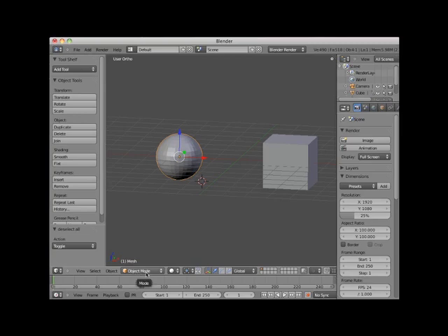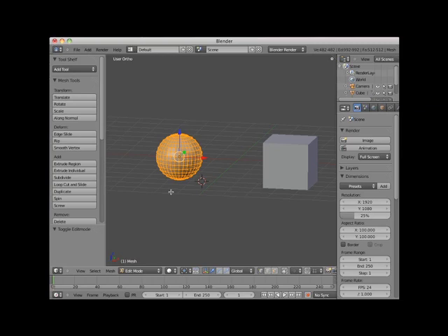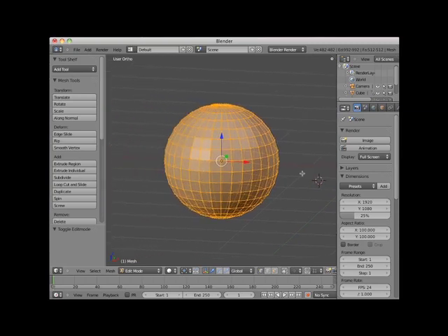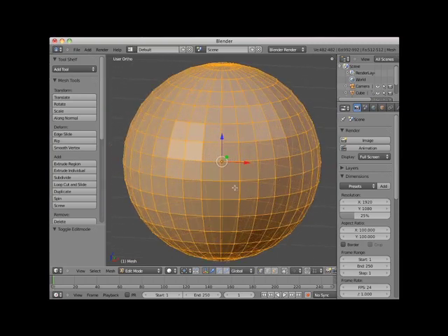When in object mode, any transformations, modifications, or constraints applied to the object will affect the mesh as a whole. A second, quite frequently used modeling mode is called Edit mode. To place an object into Edit mode, click on the Tab button. I will zoom in a bit here so that you can see this closer. In Edit mode, we can see the individual components that structure the polygonal mesh. By default, all of these subcomponents are selected, and thus it looks all yellow.